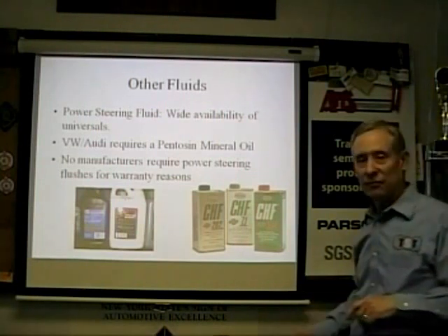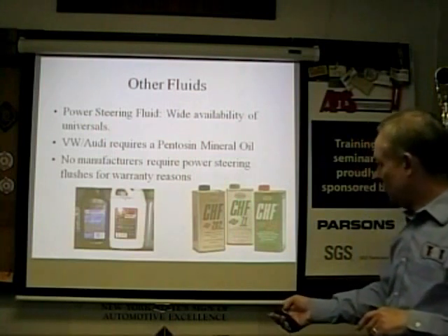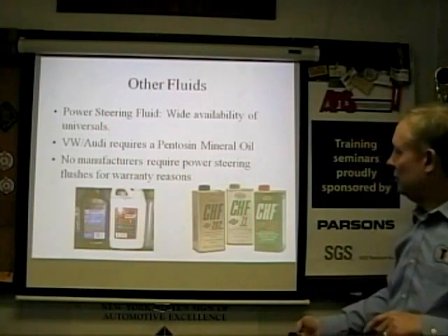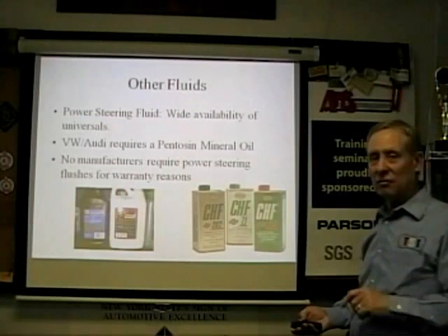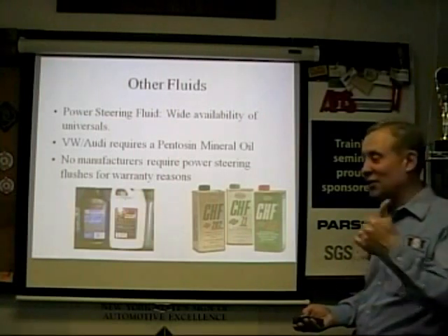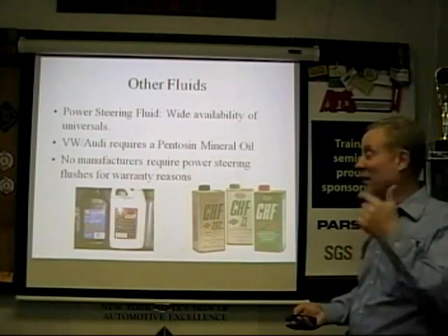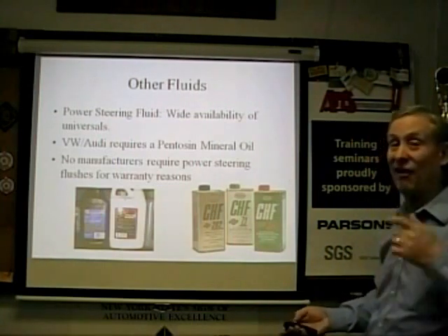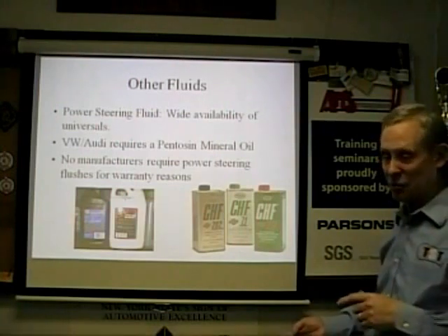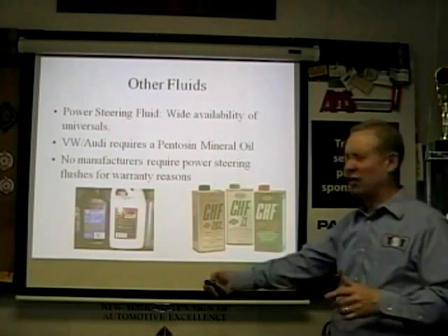And the same thing even over there, the Napa and the Run Right stuff. You have to be careful. Make sure it meets Honda spec. Honda is very fussy with power steering fluid, just like I said with coolant and engine oil. Read the spec, read the label. Don't use stuff if it doesn't have the spec on the label. Don't believe the salesman who says, this is good for everything.